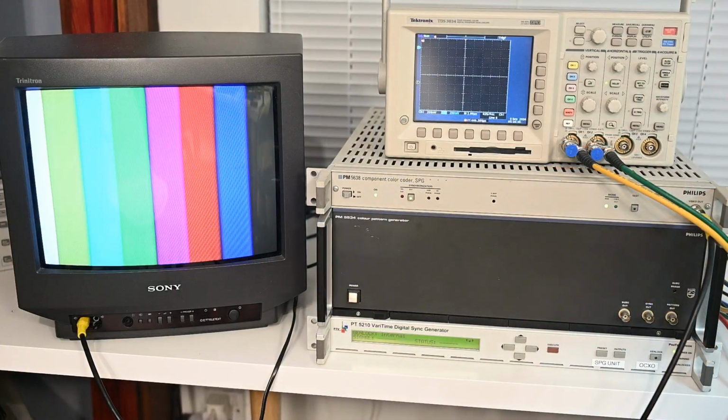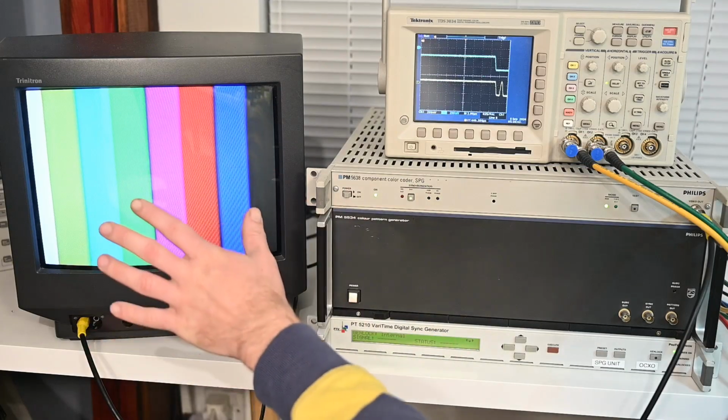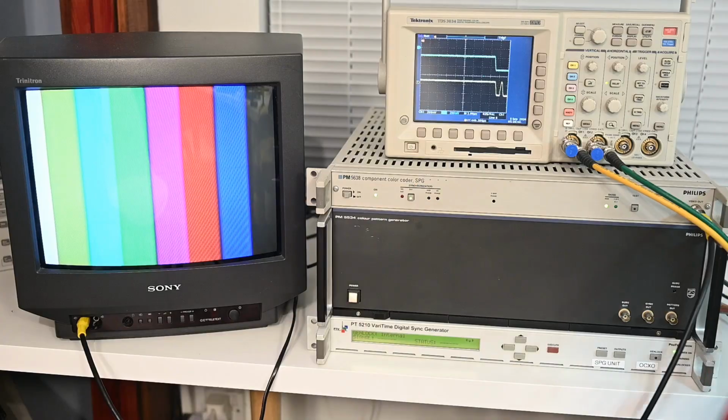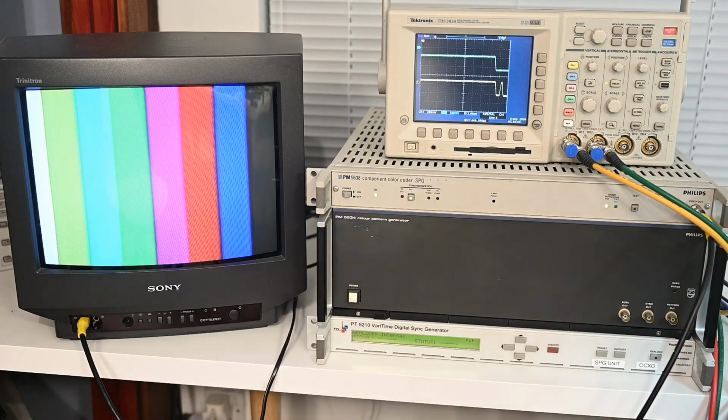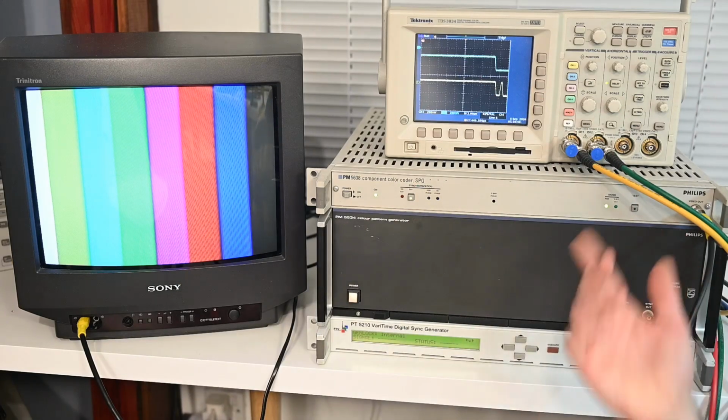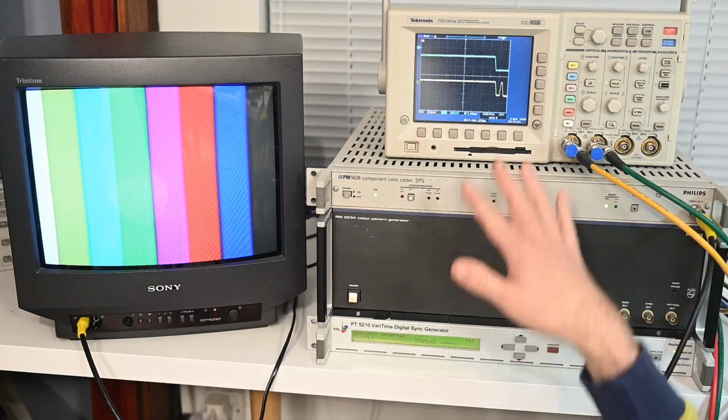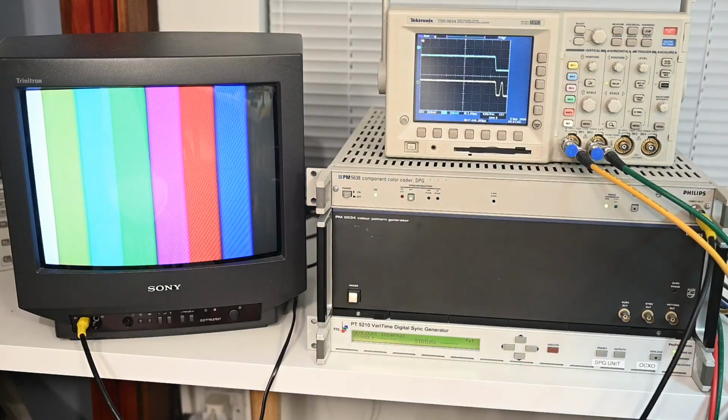Now, before we can use the Kona with this PAL coder, there's a little bit of setup that we have to do here. Presently, we're looking at the AJA color bars, and that's coming from the Kona through these three RGB cables, and I had to move the unit because my computers are over on the other side of the room. Looking at the screen here, everything looks fine, but if we have a look at this oscilloscope, well, it's not really working. I've set up a video trigger here on channel 1, which is the composite output of this unit, but it's not triggering. What the heck's going on?